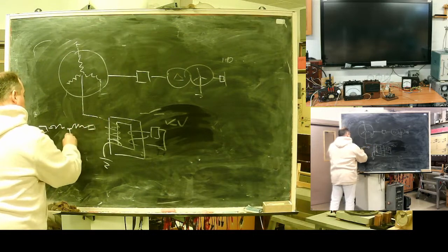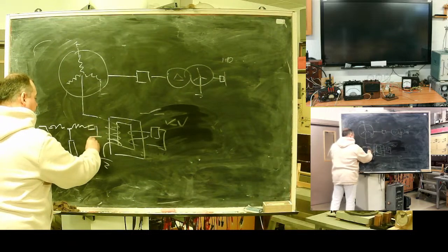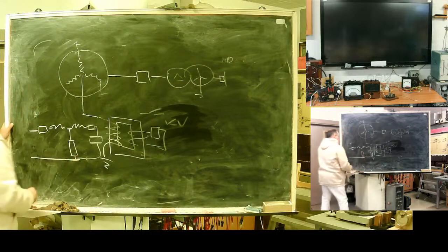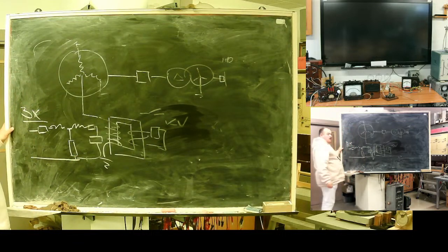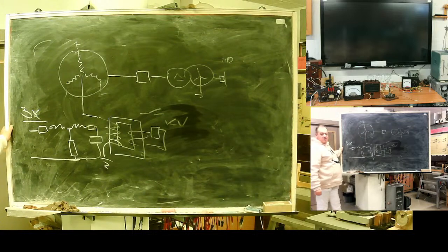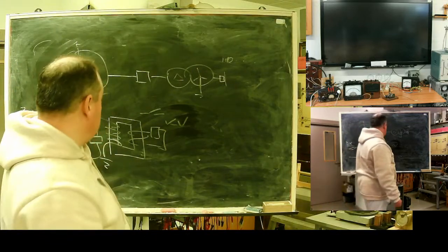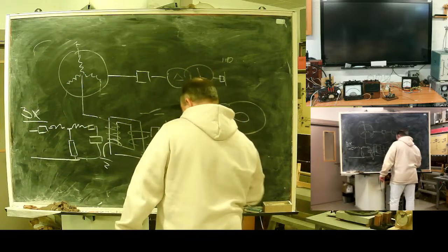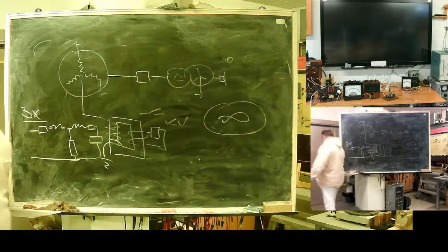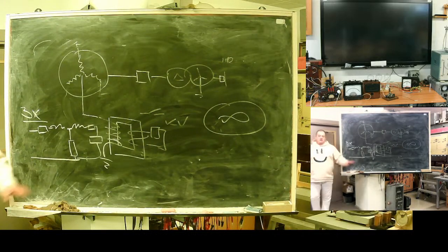Our relay has something like this, multiplied by 3. It's a very high resistance. So for zero sequence, there will be no zero sequence current. For zero sequence, we will see infinite resistance. It's for large machines.